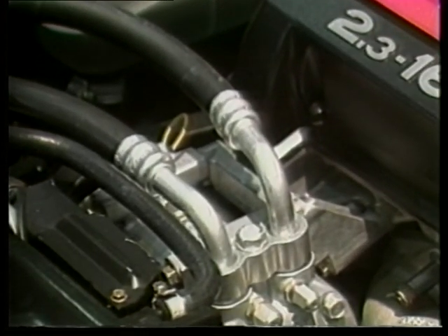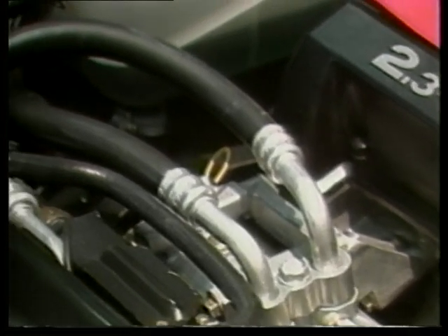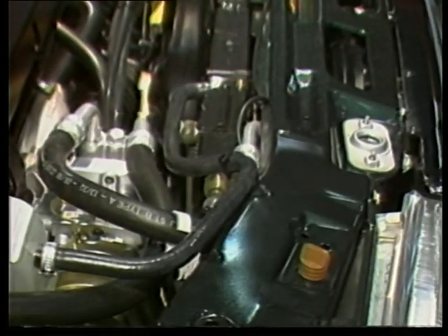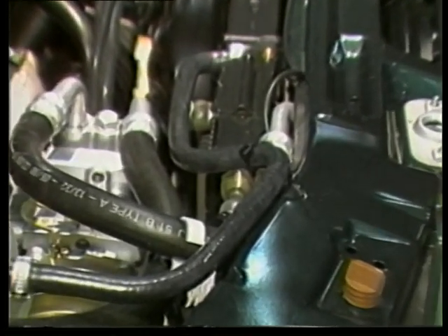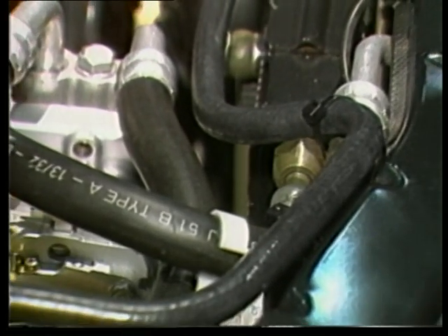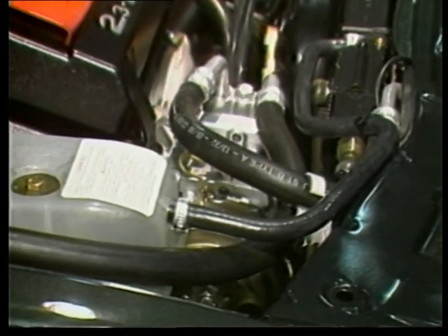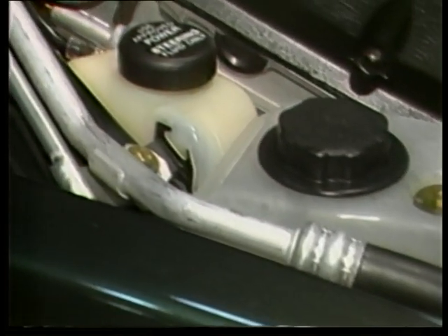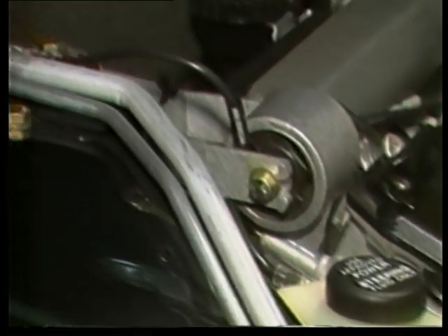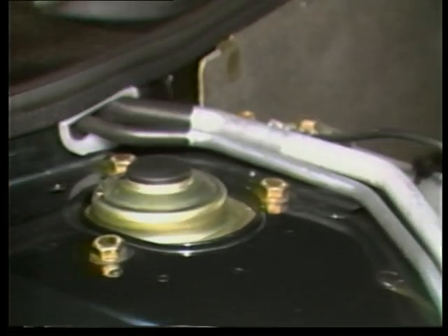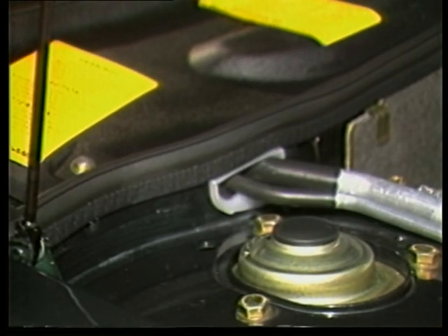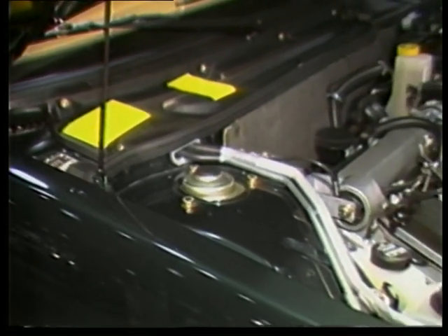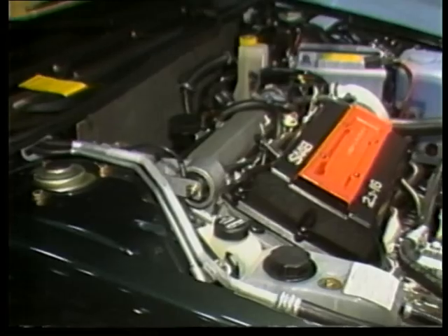Refrigerant hoses and lines carry R12 to each component in the system. They are very high-pressure hoses and tubes designed to withstand compressor vibration, extreme temperature changes, and high pressure values. The air conditioning hoses and lines carry refrigerant from the compressor to the condenser, to the evaporator, and then back to the compressor. Clamps or straps are often used on long sections of line to prevent excess vibration and damage.